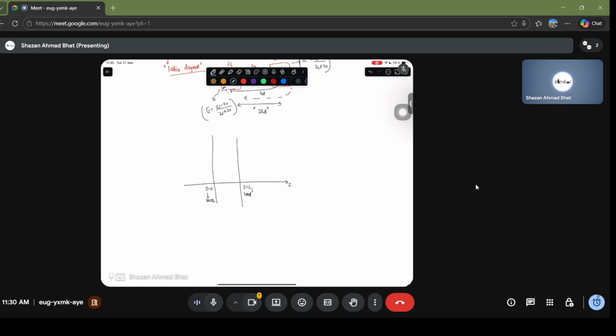Okay. And then you draw the normalized time here, which is time divided by the delay time. You have 1, 2, 3, 4, 5, and so on. So at this point, the time equals 1 TD, time equals 2 TD, and so on. In 1 TD, the waveform reached the load end, and it reached up to a certain voltage value, let's say V1, and then it gets reflected and reaches the source end, and let's say it reaches a value of V2. Then it again comes back, and in 4 TD it again reaches the source, but obviously with amplitude, let's say V3.